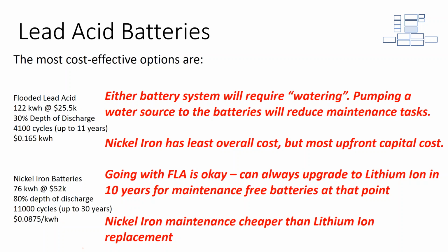And so if you go from an approach of, well, let's install all of the infrastructure, but put a really cheap battery in line and we'll run it into the ground, and then 4 or 5 years from now swap it out with the latest and greatest battery technology, that's not a bad strategy to consider, particularly if you're budget constrained. It might be that you do an 8 kilowatt commercial battery system today, even though the commercial facility load might be 1 megawatt, just to demonstrate the savings and dip your toe into the pool before you dive in.